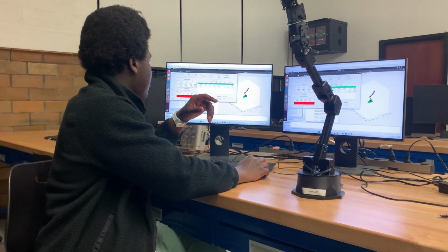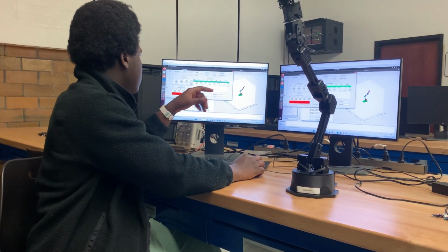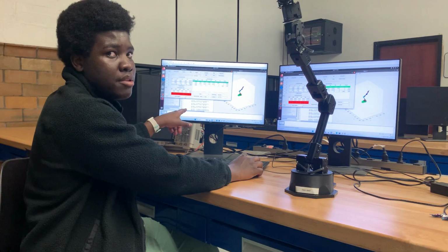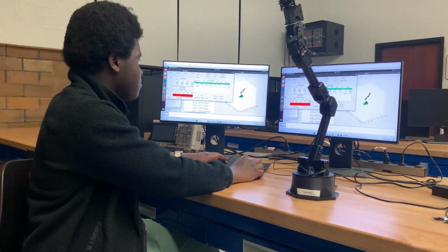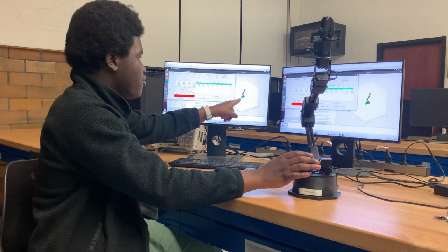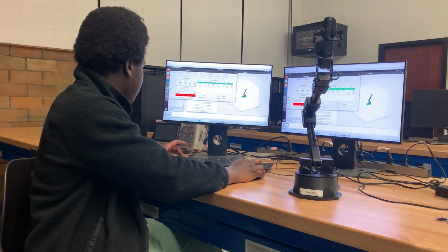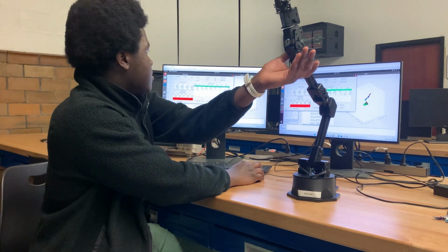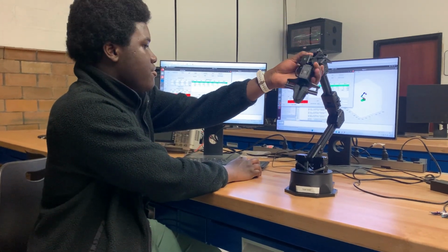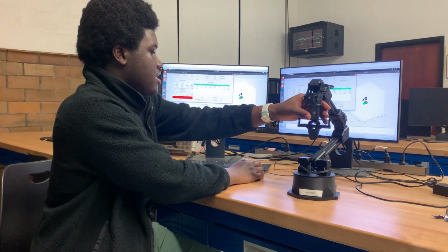Now, I'm going to click compute inverse, so we can see all the different inverse kinematics positions. So we're going to move to solution 2. You can see the movement. We can move back to another solution. Then also, you can even see when there are infinite solutions at a particular point.